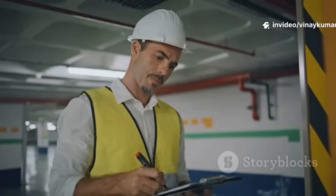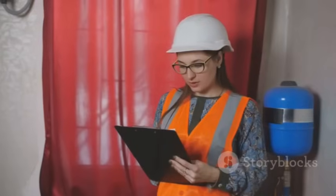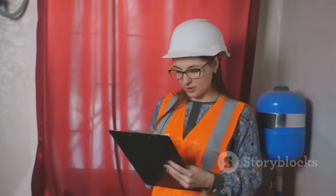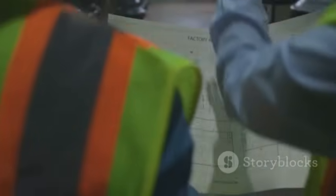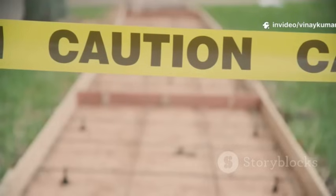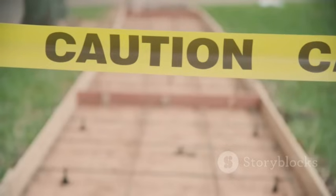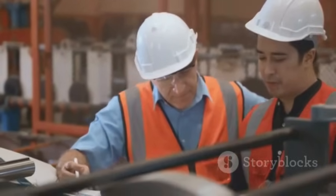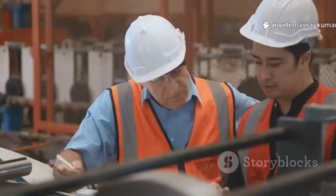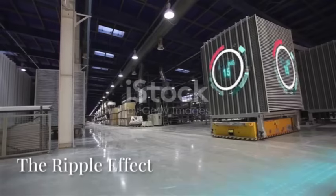The completed permit must be kept on file until the hot work operations are finished. This provides a clear record that safety protocols were followed. The hot work permit system is a classic example of an administrative control. It doesn't physically prevent a fire, but it creates a robust administrative barrier that makes a fire much less likely. It's a simple but incredibly effective tool for managing one of the most obvious and severe hazards in any industrial facility. It's about treating fire with the respect it deserves.